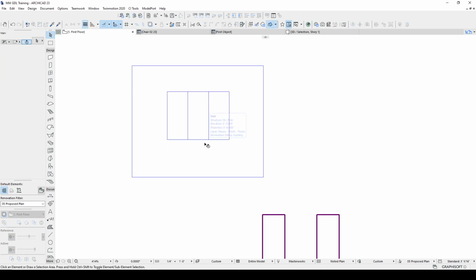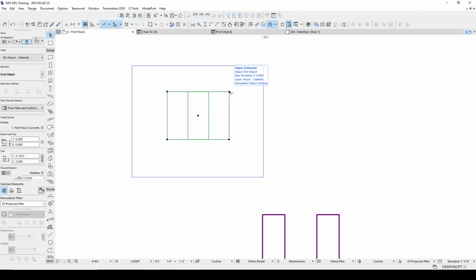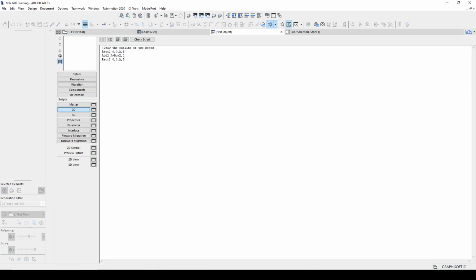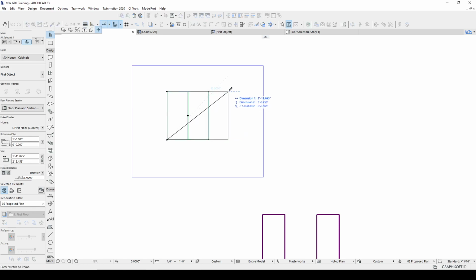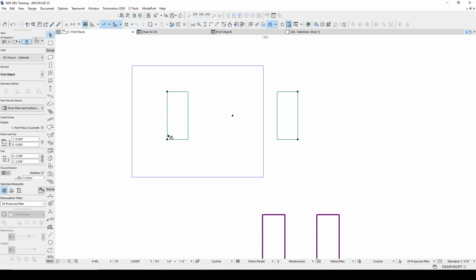So what is it doing? And this is a very typical way of programming where you try something, you get a puzzling result, and then you realize what you did, you correct it. So don't be embarrassed by that. It's just a process. This is box X. So I'm feeding in now not A, but the width of the box. Now as I control the width of the entire object, it's placing a box at 0 and a box at the A dimension.